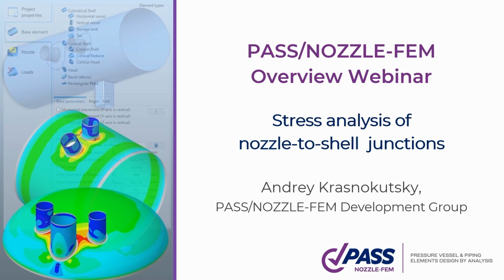All calculation methods can be divided into two types, the so-called design by rules, or design by formulas, and design by analysis. Design by rules is the calculation of vessel safeties such as strength, stability, buckling, tightness, and others using formulas. The formulas are in the codes such as ASME 8, Division 1, Division 2, EN 13445-3, and others. And the calculation is carried out for certain standard elements: shells, heads, nozzles, flanges, supports.